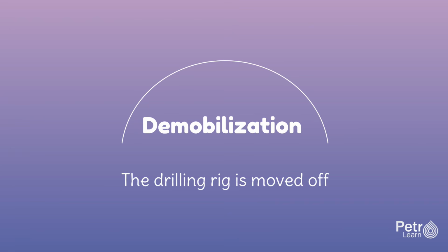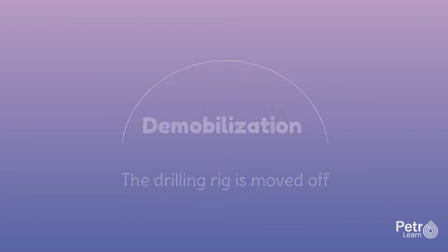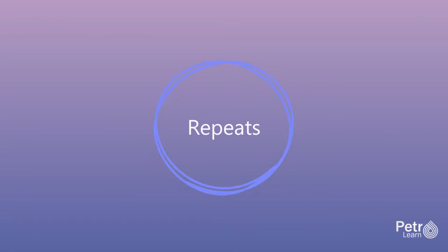The drilling rig is moved off the well once the Christmas tree is installed and the well is flowing. Rig demobilization reverses the assembly process. Components are disconnected, lowered, and loaded onto trucks. The site is restored to the extent required by regulations, with the wellhead and access road remaining. The rig moves to the next location to drill another well. For the rig crew, the process repeats, with each well presenting unique challenges based on the geology, depth, and objectives.